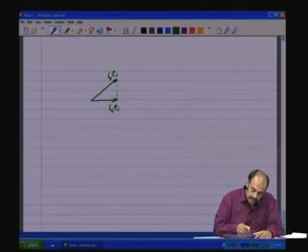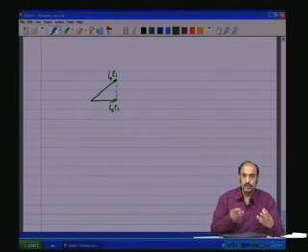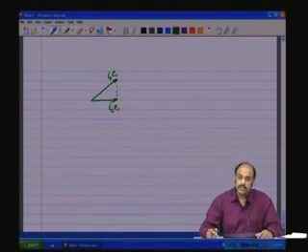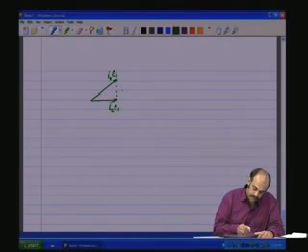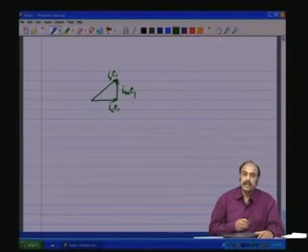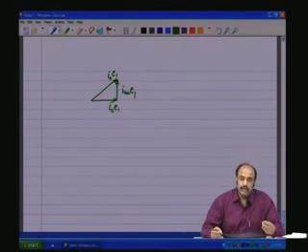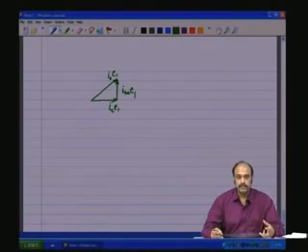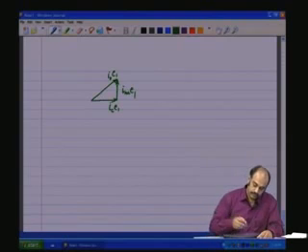IC into E1 is the active power, that is the loss component, which is drawn from the source, and IM into E1 is the reactive power that is drawn from the source for setting up the magnetic flux in the core.